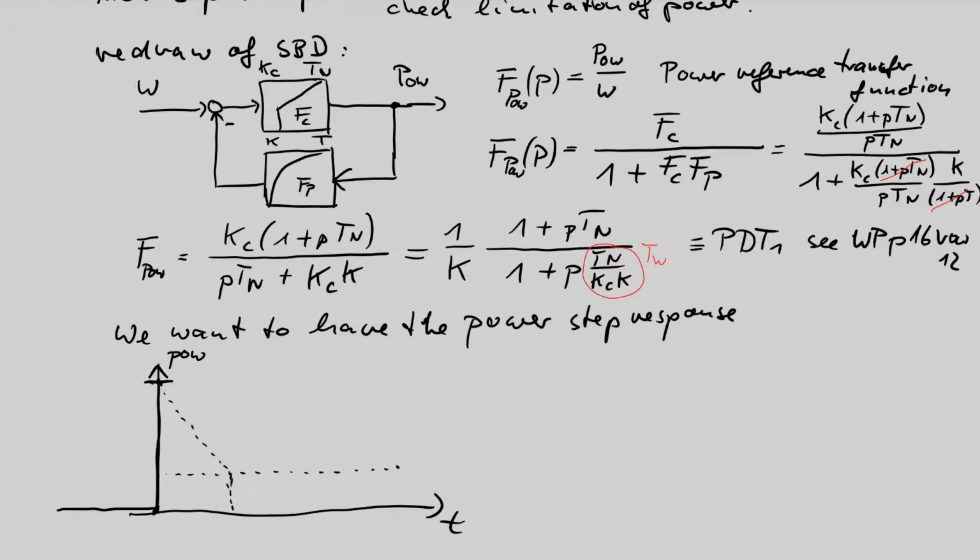So we need how large this time is, and then we know the power final value is like this. We want to have the peak value, and that is the most interesting thing: can our motor deliver this peak? We should have a value for the final value, and we should have a value for the time. Then we know all about my power signal, and if this can be realized, if my car can do this job, if my wheels can bring this power on the street.